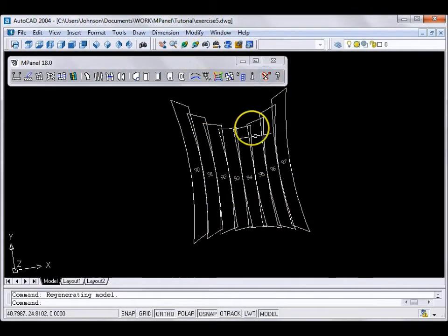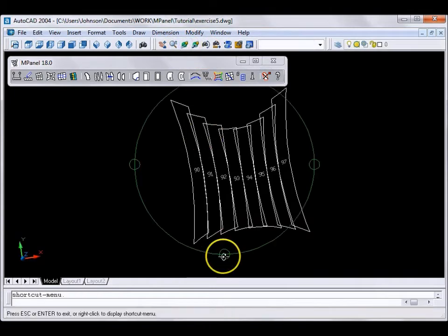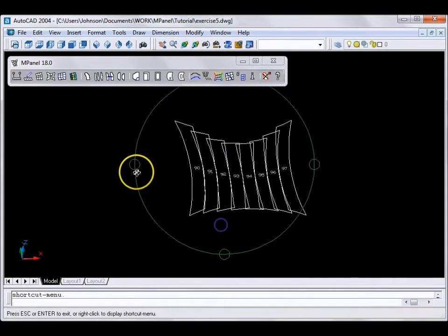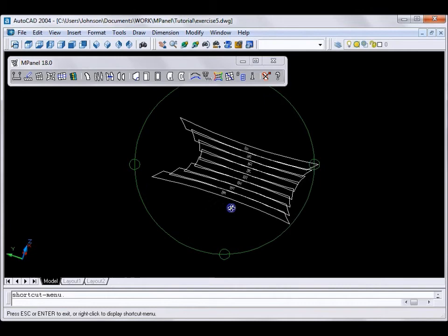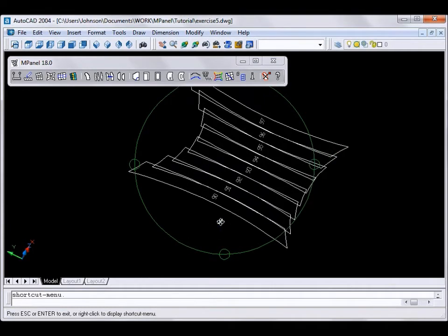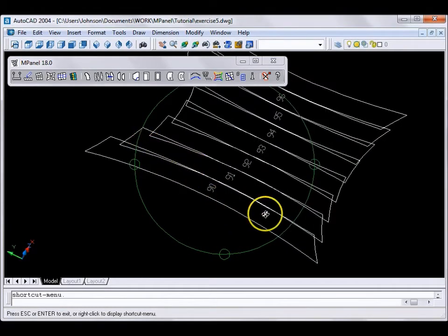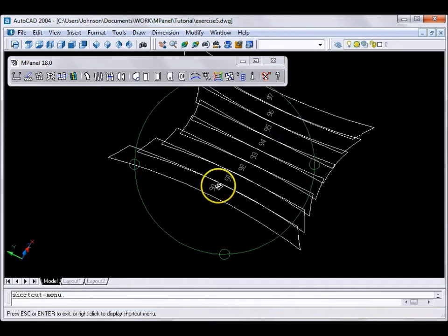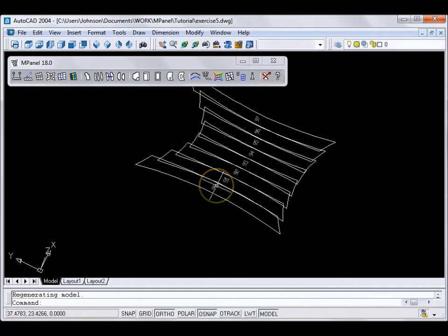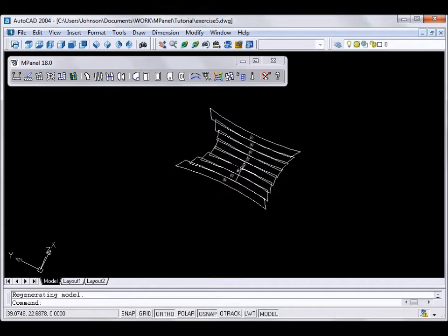However, when we use simple paneling, the panel size is dictated by the program, and it can only make numbers of panels that fit evenly into the mesh. Furthermore, the panel seams are always curved, like the mesh, which can cause difficulties during panel construction. In order to achieve more paneling versatility and control, we panel by making cross-sections. Using cross-sections allows us to customize the size of our panels, and it results in straighter seams.